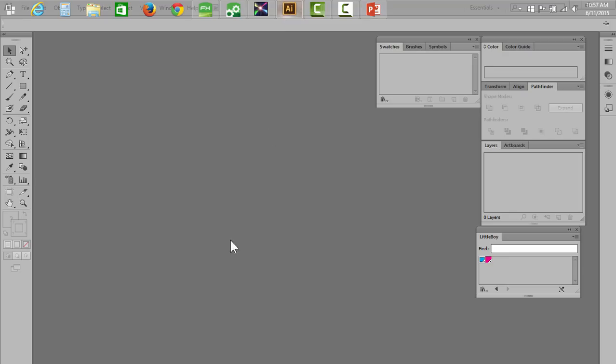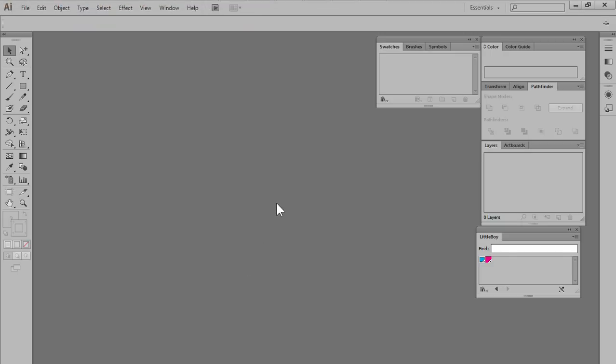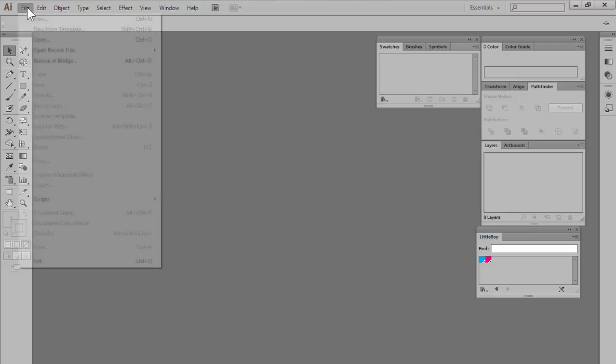Let's start with Illustrator. Now, by the way, the first thing I had to do in Illustrator, and what you'll need to do if you're going to use it for contour cutting, is create a color swatch down here. You have to actually create this swatch color here that's named contour cut. You'll have to make one that's called perf cut. You have to create this swatch table here, and that's a separate subject, but it is something you have to do. There's lots of stuff online to show you how to do that.